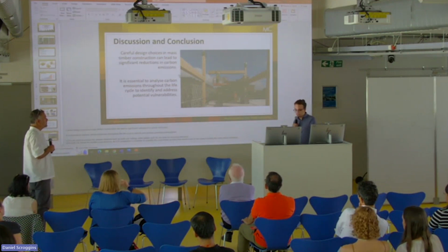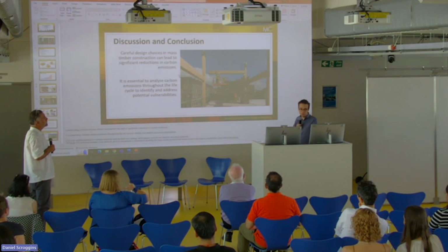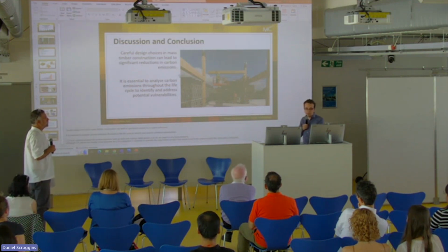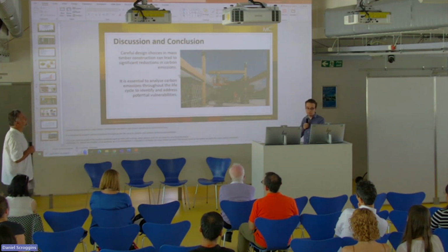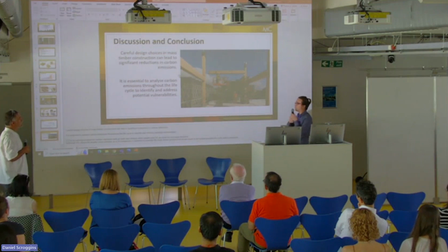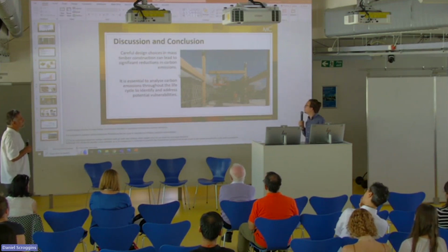They're already doing it pretty much all over the planet, and the way to build this is to take care of not exposing timber to the outside element, the outside air. And in the construction phase, as we can see here, the ideal thing is to protect the exposed parts where the veneers of the timbers are.